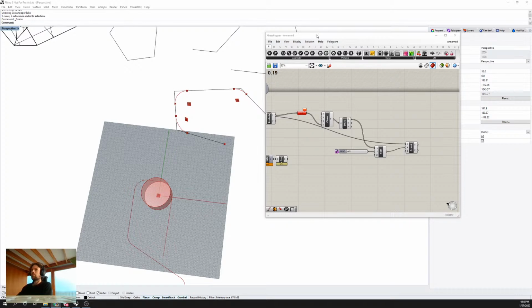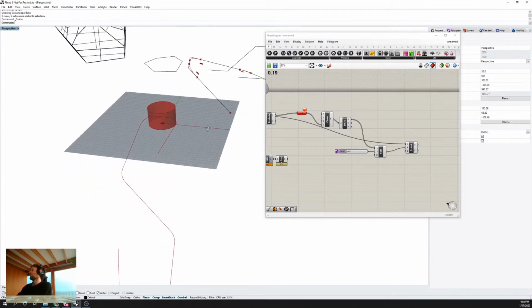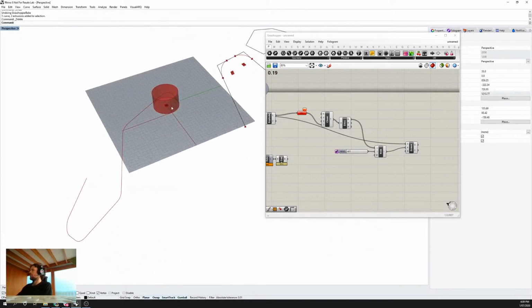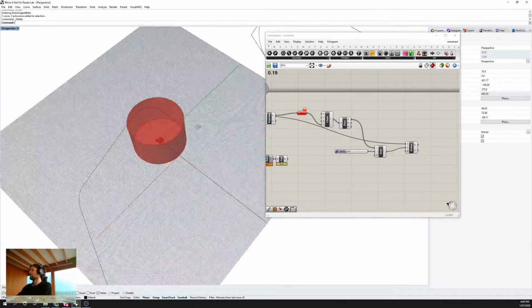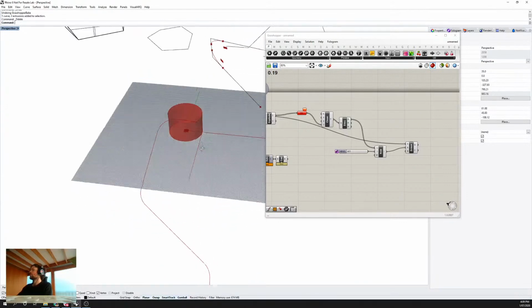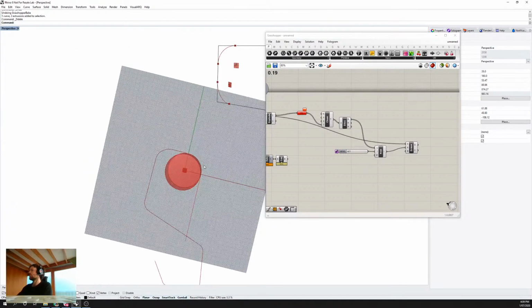Okay, so where we left off, just so I could calm the dog down, as you notice, we now have no barking, is we've got a way of orienting our part onto our bender. We can preview the fillet radius, which is really nice, but this isn't actually giving us all of the information from that diagram that I sketched out initially, which is showing us things like the length of the segment of the part that has to be bent, the remaining length, and the bend angle.